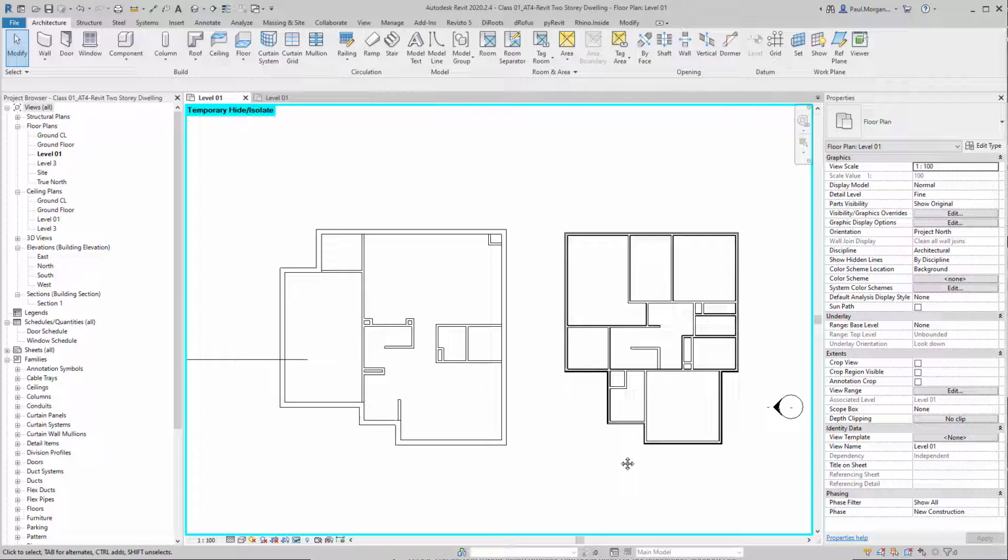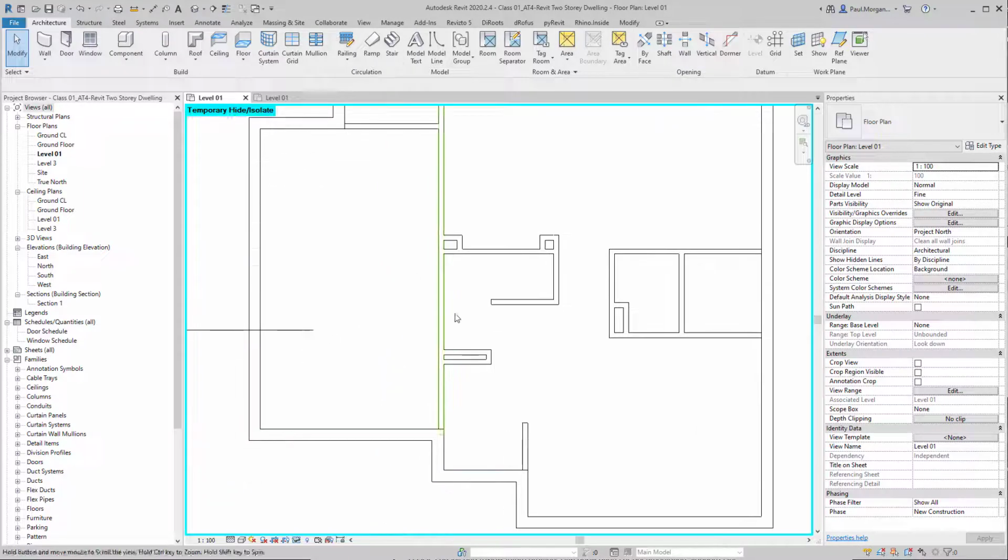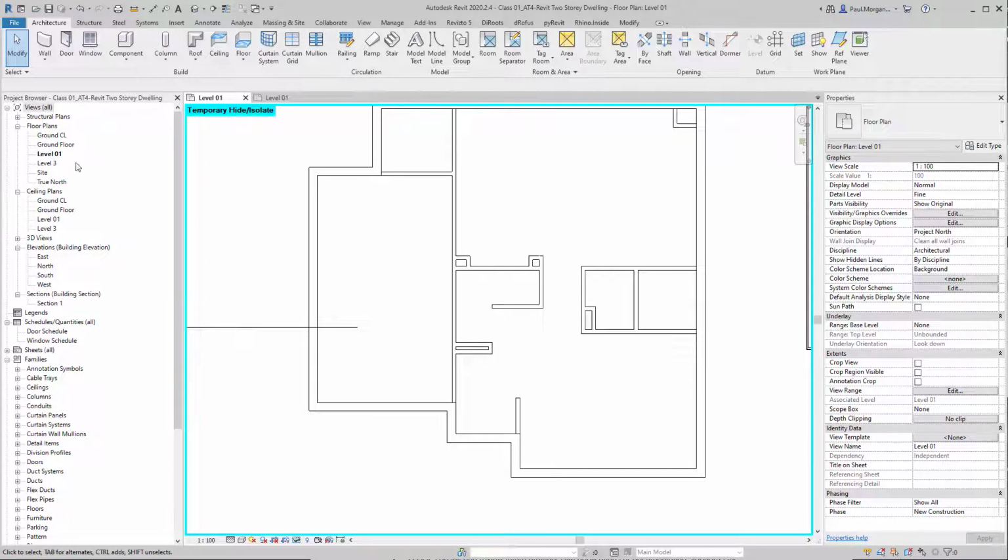And generally speaking, in a larger building, this would be your concrete core, your service core and your elevator risers and your elevator shafts, or your fire stairs. Or in a residential house, I would probably start with the stairway as well because they're the non-negotiables. They must line up. So this is our stairway on ground floor, and I'm currently on the level 1 floor plan.